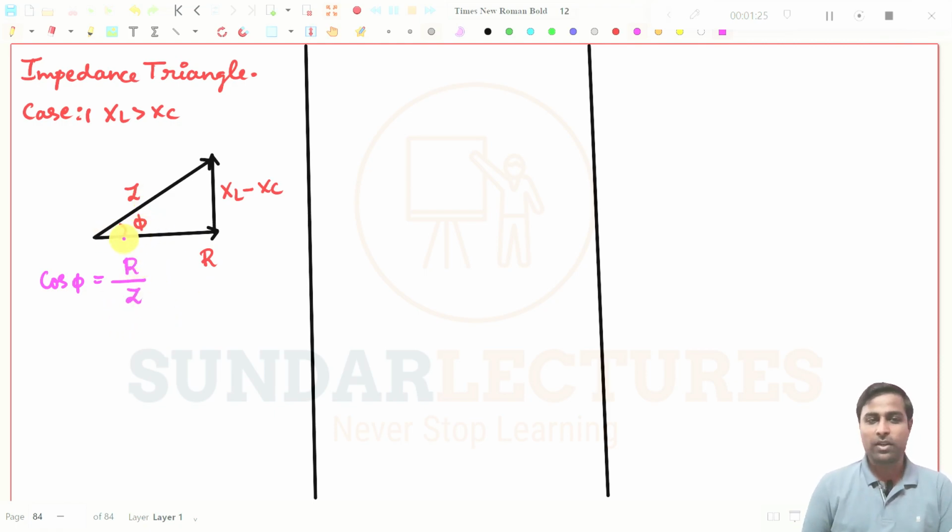We know this one. In an AC quantity, if it is the total Z, then this phasor will be, what is this one? R value plus what is this one? This one will be J of XL minus XC. We have seen this one. If you have any doubts in this one, writing the value of Z, we can go for R plus J of XL minus XC.